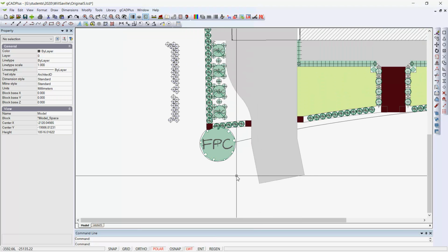So you can see it's really important to get layering correct. When we're advising students on the best approach for this, we think throw pretty much everything on layer 0 and separate it all out at the end rather than do it as you are working through the design.